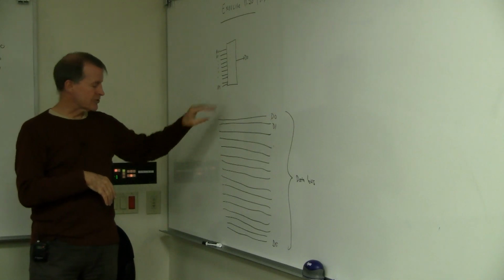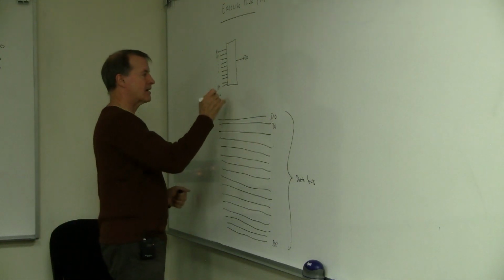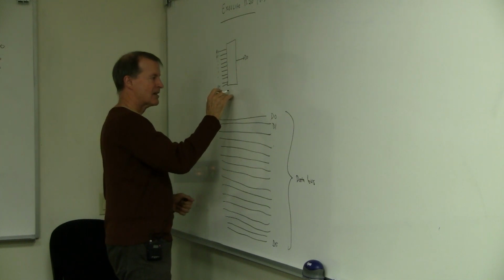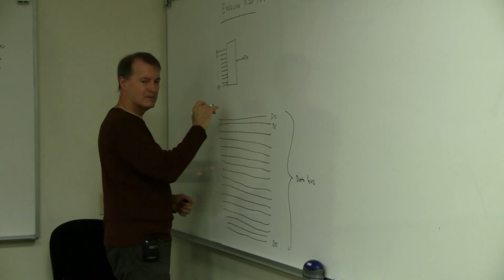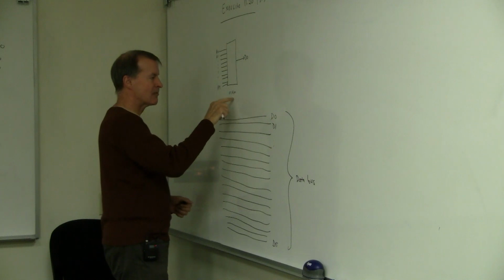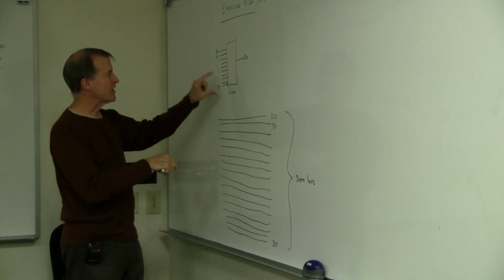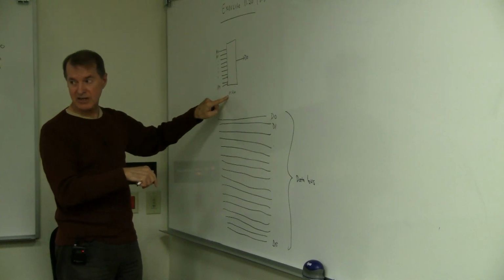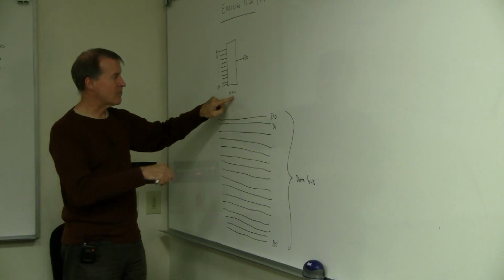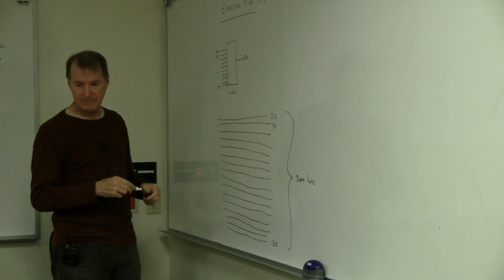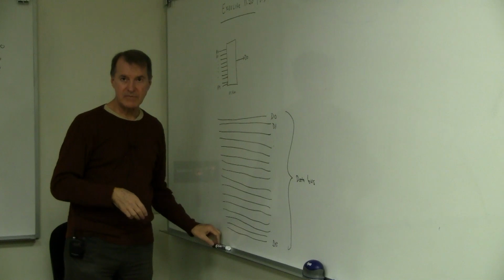And then the first number, when you have an, I forget the letters that I used. Was it N by K or N by M? Yeah, you use N by M and L by M. Here, if this is an N by M, this N is not the number of address lines. This N is 2 to however many address lines there are. And this M is how many data lines in parallel coming out of the chip there are. Okay, are we good?